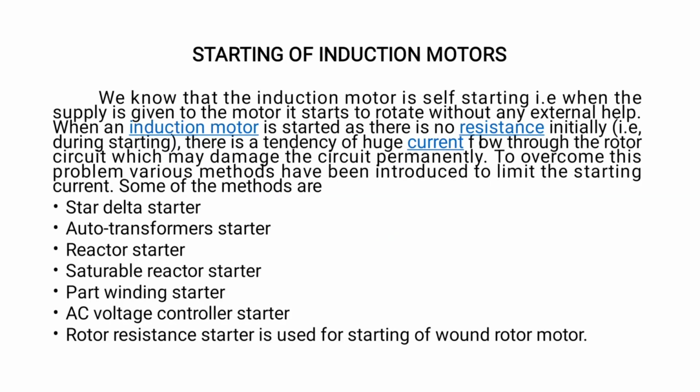Starting of induction motors. We know that the induction motor is self-starting, that is, when the supply is given to the motor, it starts to rotate without any external help. When an induction motor is started, there is no resistance initially. There is a tendency of huge current to flow through the rotor circuit, which may damage the circuit permanently.